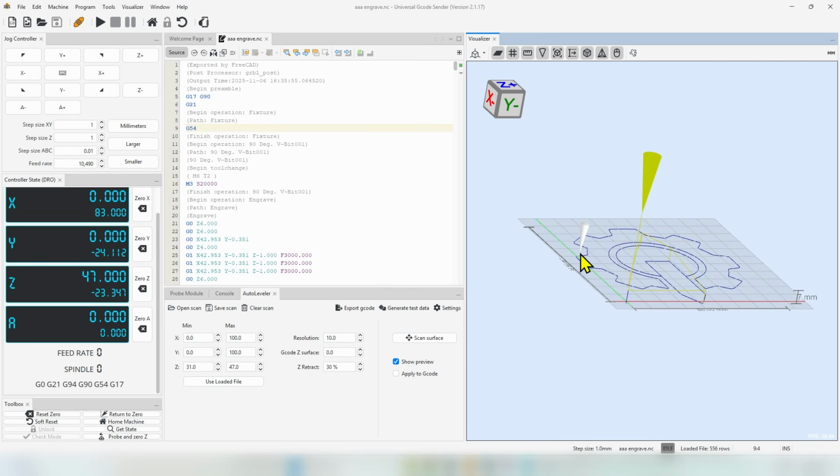It should be solved in the future probably, but until then I suggest testing it before running a probing sequence of hundreds and hundreds of points, which take a lot of time and losing everything. First, test it on a 4-point scan. Click on the Save Scan button and see if Universal Gcode Sender freezes. If it does, remember the solution is to close the visualizer and then save the scan.